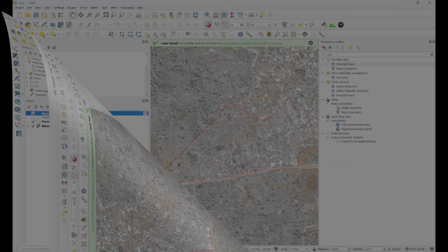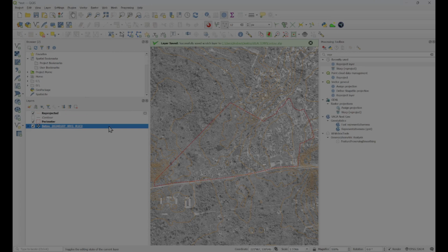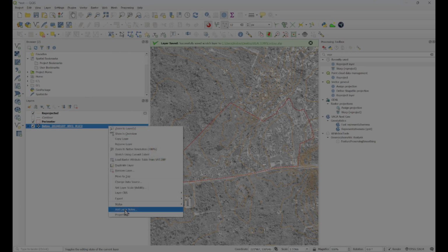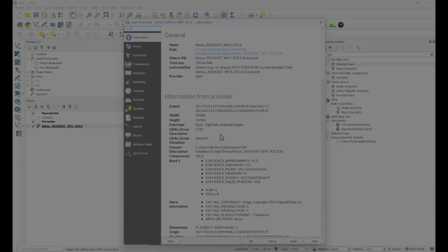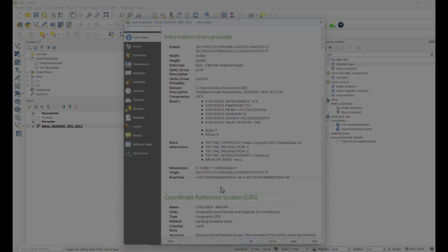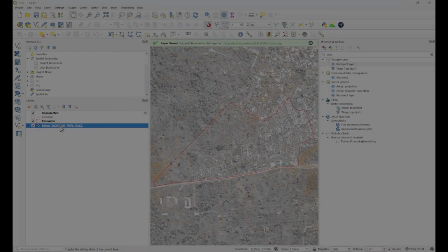The same for a raster layer. Let's see this raster layer. Click twice to check the type of projection it has. This layer has geographic projection. With this layer I wouldn't be able to make any type of terrain analysis, so I need to reproject it in UTM projection. I type warp.